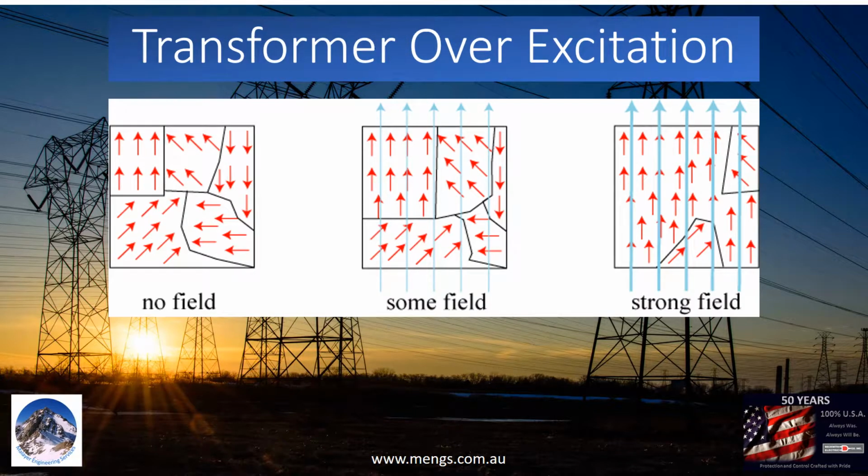When an external magnetizing field H is applied to the material, it penetrates the material and aligns the domains, causing their tiny magnetic fields to turn and align parallel to the external field, adding together to create a large magnetic field B which extends out from the material. This is called magnetization. The stronger the external magnetic field H, the more the domains align, yielding a higher magnetic flux density B.